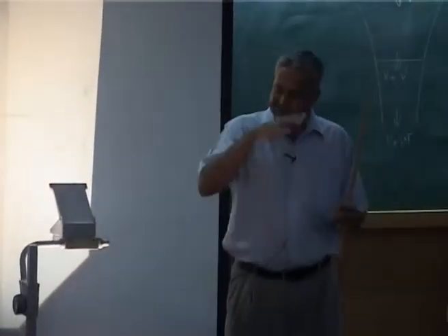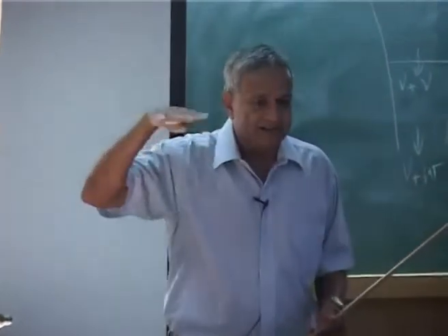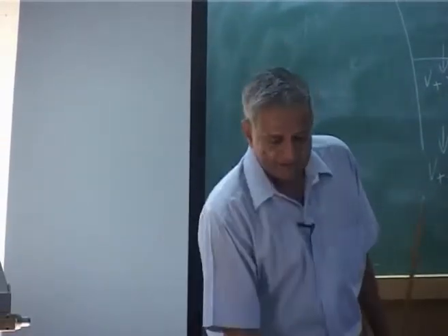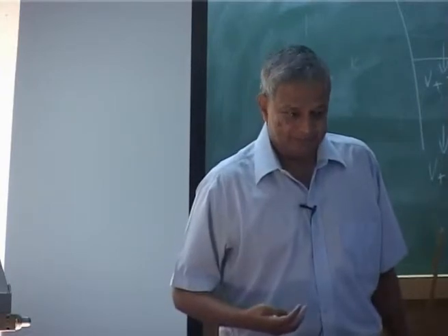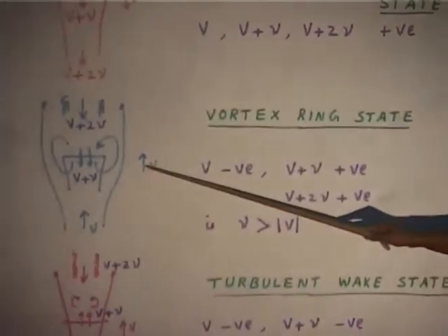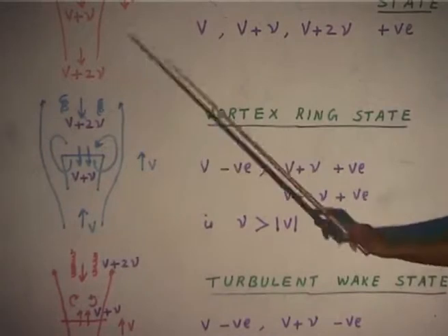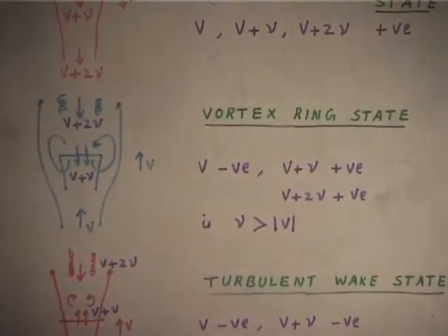That is how the rotor is doing the work in pushing the air down, that is how it is staying. So, at the rotor disc, the rotor is pushing the air down, but from the far field the flow is coming up. You understand? That means this flow here and these are coming up, but if you look near, you have just started descending. That means the velocity V, capital V,